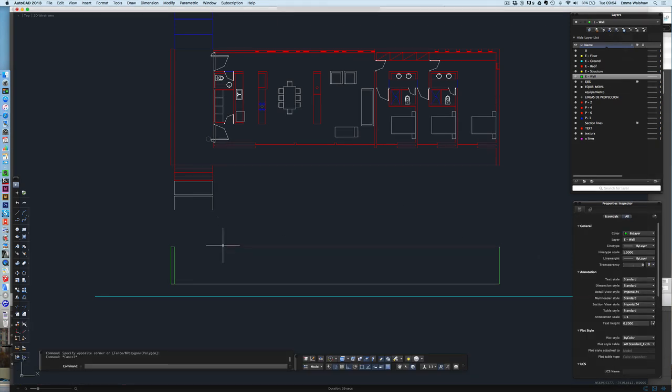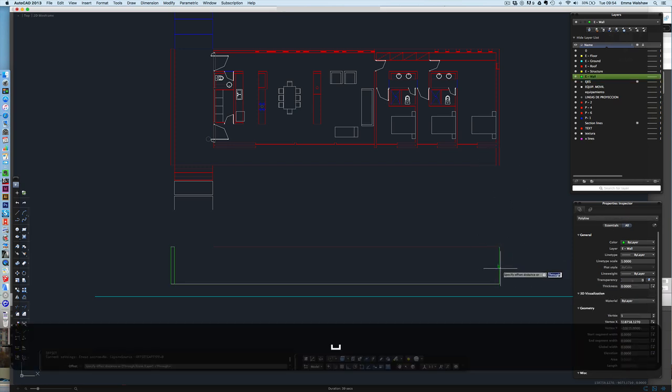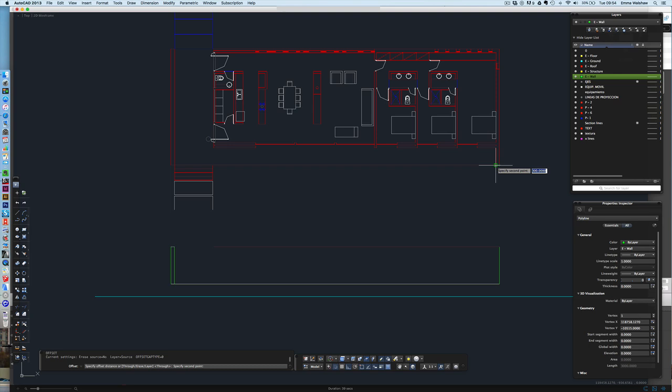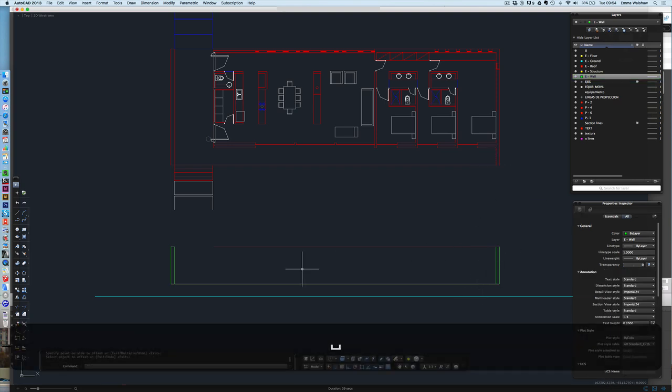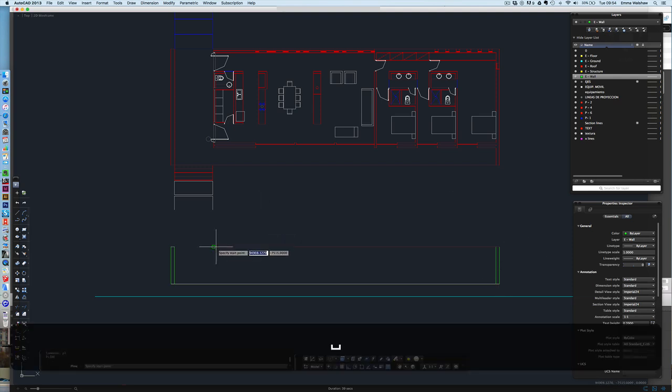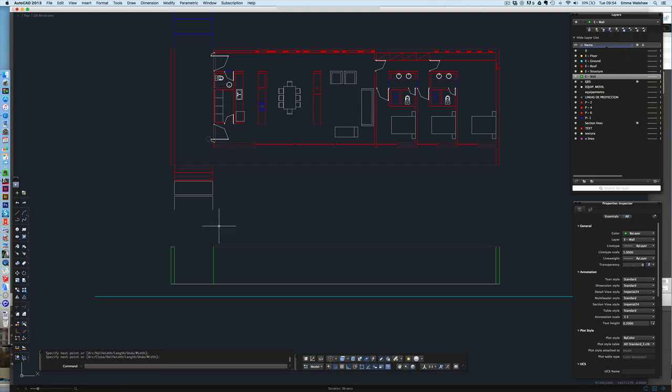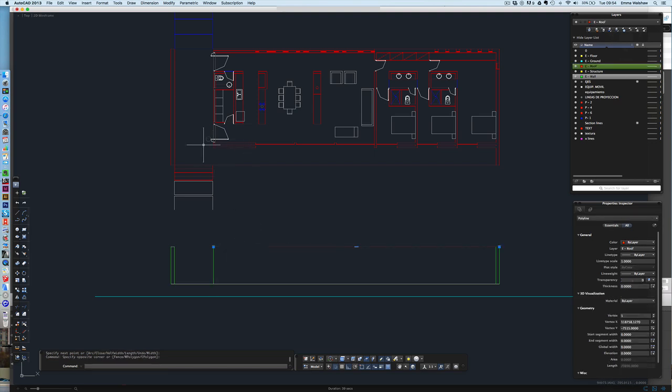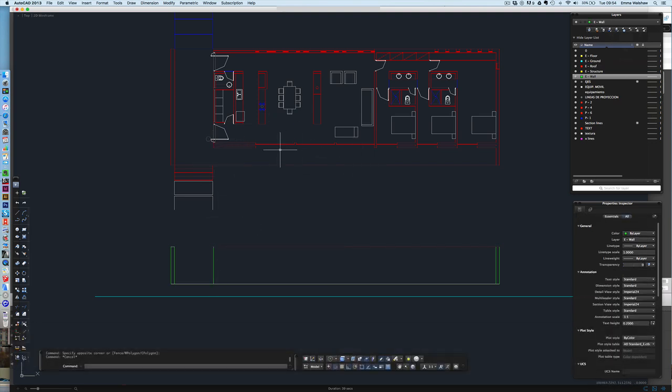So let's add a bit of detail to these walls. On this wall here, you can see this extends beyond the line of the building here, so we need to just add that detail in. So I'm just going to offset that wall. I'm going to offset by the distance that's above here, which is 300. We've got that there. We also need to start adding detail to this side, so I'm going to check I'm on my wall layer. I'm going to draw my line down because we've already lined that roof line up with the building. And now let's start putting in some of these walls as well.